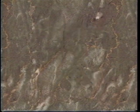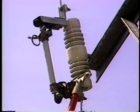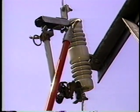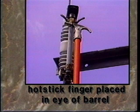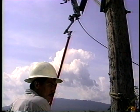Opening the cutout. When possible, remove all load from the line before opening the cutout. An inspection of the cutout should be made to detect abnormalities that might cause an accident. If problems are detected during the inspection, follow the work methods established by your company to correct the situation. The hot stick finger is placed in the eye of the barrel. Look away from the cutout, then with a quick, forceful downward movement, open the barrel.